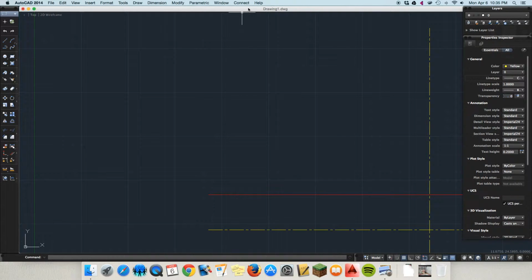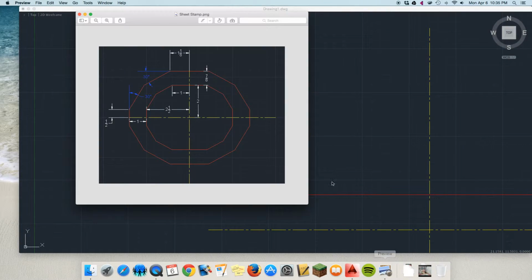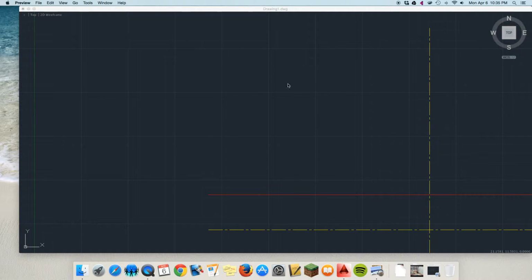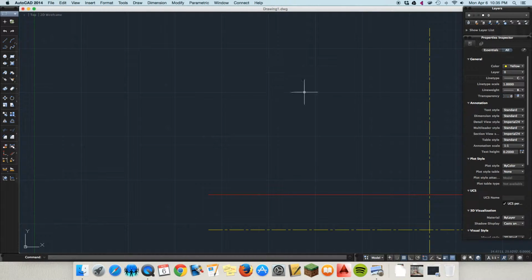Okay. Now I'm going to take care of the other line that's on top, and then we'll trim in just a minute. This line up here, if you look towards here, is actually 7/8 of an inch above that 2-inch line. So here's how we do that. We haven't typed in fractions in the program before, so I'm going to show you how to do fractions, and then I'll show you how to do mixed numbers, which comes up. I'm going to click offset again because we're going to make another parallel line to that. It wants the offset distance, so I'm going to do 7/8. Slash is the one that's underneath the question mark on your keyboard. I'm going to hit enter. I'm going to choose that red line. I'm going to move upward and click. Okay, notice it made an exact copy of the red line this time.